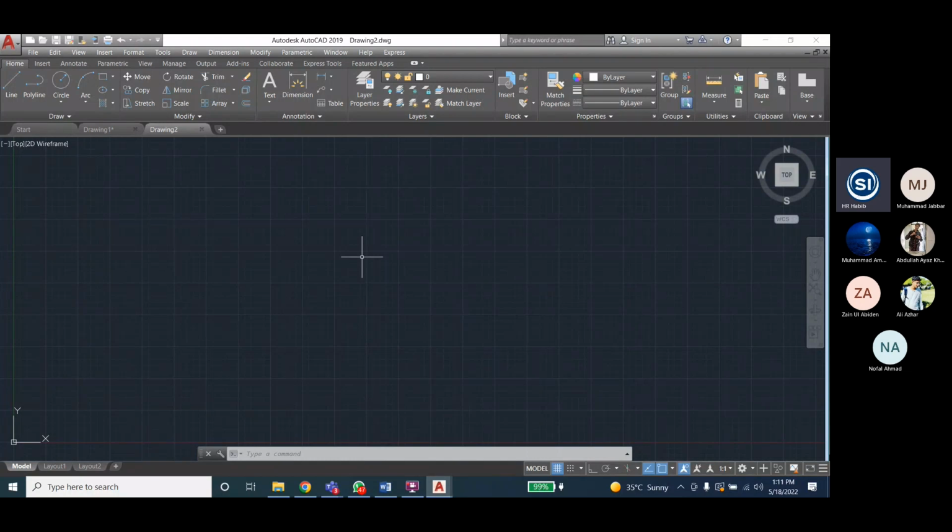So specify base point. We are using the move command. Okay. Specify base point, for example this base point. So we want to move, for example. So you can move aside like this, and again the window is empty. Here you can try. Acha, in the Modify panel, just click the move command. In Modify, there is Move. And also you can write move, that is available too. Okay.